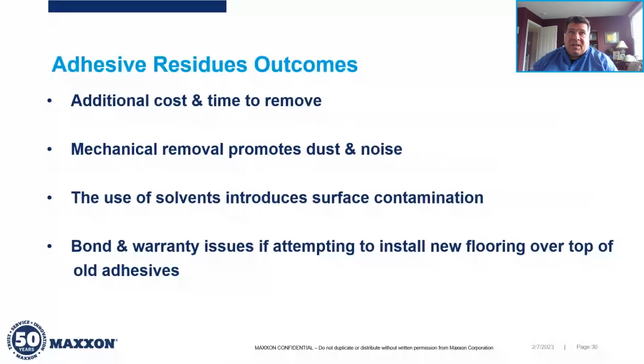Okay, well, it gets the adhesive off the floor, but it leaves surface contamination and even contamination that's within the slab. And then we're talking about the same thing of bond warranties, issues, with things being applied over top of these old adhesives and whether or not they're actually going to stick.